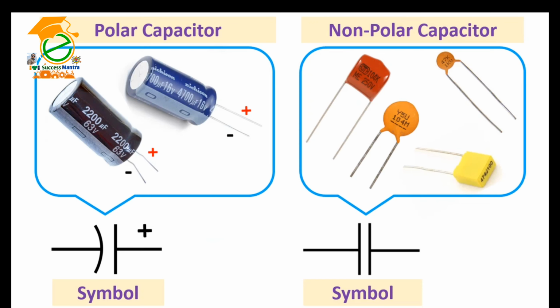Electrolytic capacitors are typically polarized. This means that one pin needs to be connected to the ground side of the circuit, and the other pin must be connected to power. If it is connected backwards, it won't work correctly. Electrolytic capacitors have the value written on them, typically represented in microfarads.